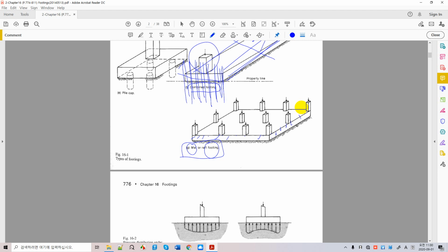So we need some help from finite element analysis to calculate the moment and shear diagrams and to place rebar in between. This is a two-way continuous beam. Our moment diagram looks like that, which is calculated easily based on finite element analysis. We're going to take a look at the finite element model later.